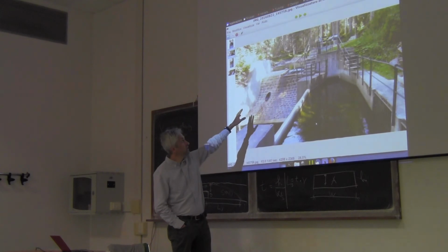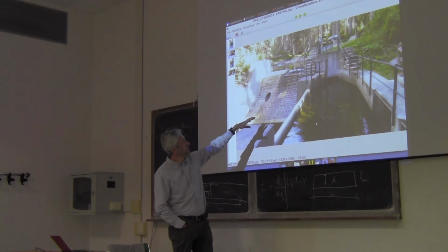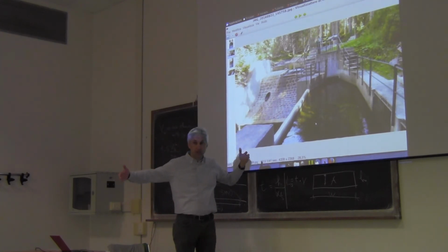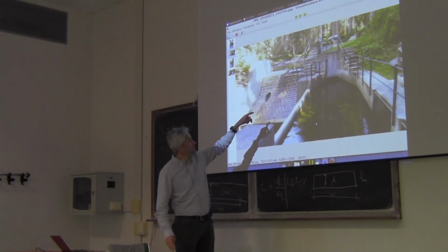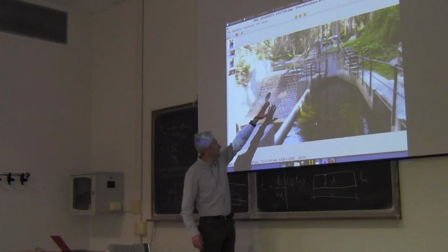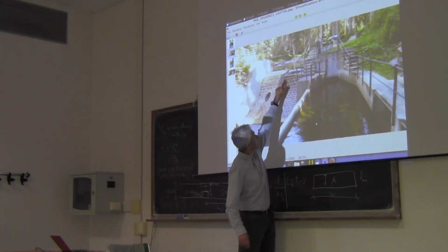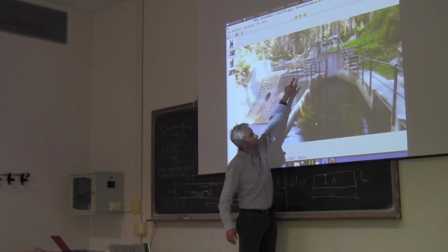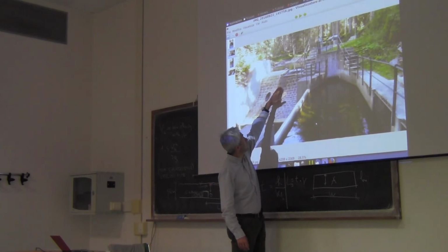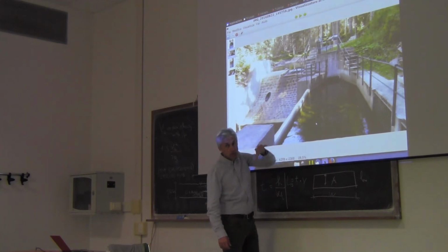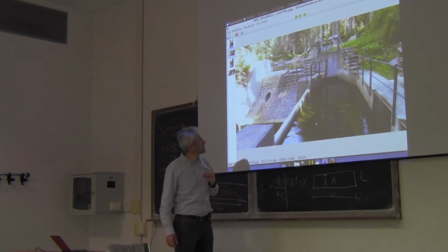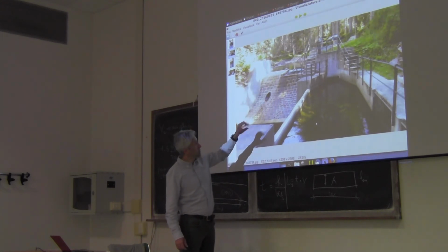They want to keep some reservoir upstream in order to allow for compensation. And this is a distinguishing feature of this plant: they didn't have much space to make a lot of facilities on the sides, and therefore they decided to withdraw water through what is called a bottom grid. So the water withdrawal is occurring here. This is a grid, and so you have water flowing over this grid with priority because it's at a lower level, and therefore water is withdrawn through this priority grid.